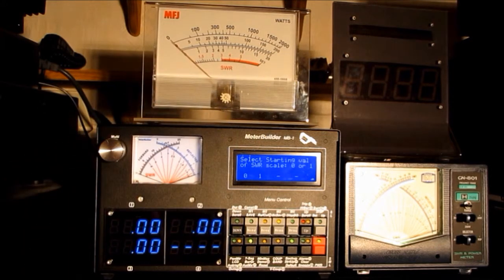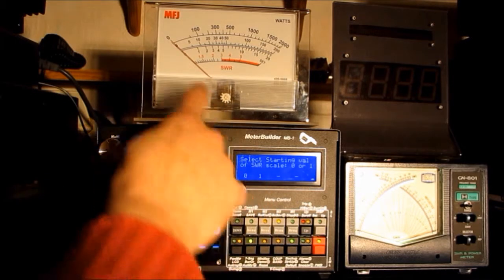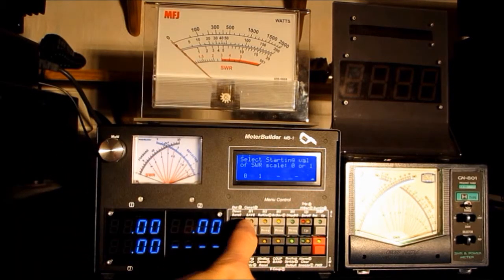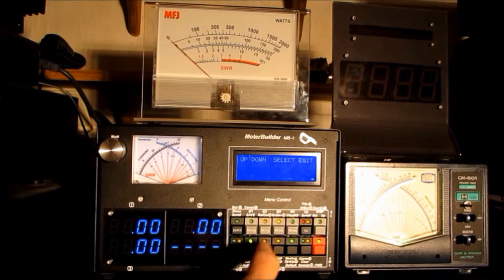As I mentioned before, the software will accommodate meters that are 0 based, and the software will idle the needle at a 1. So you may have a very nice meter that you'd like to use for power, and there's also a scale on there that you might want to use for SWR, and because it's 0 based you wouldn't be able to use it otherwise had we not built that capability in. But in this case the SWR starts at 1, so 1, which is menu item 2, is the correct one to pick.